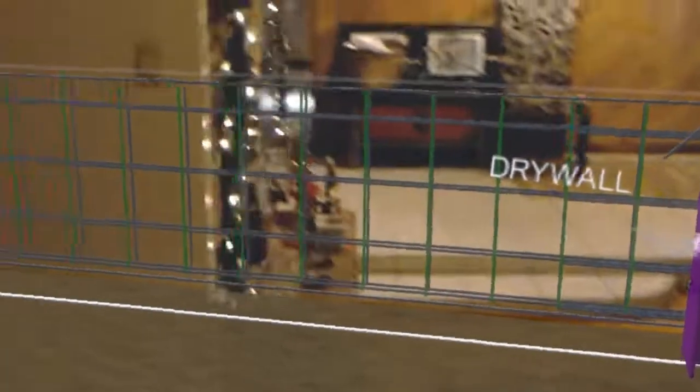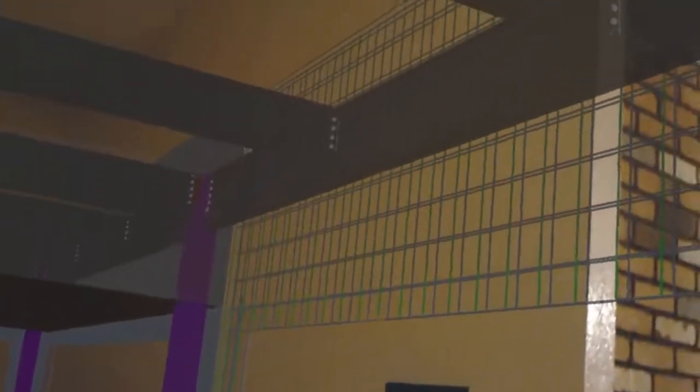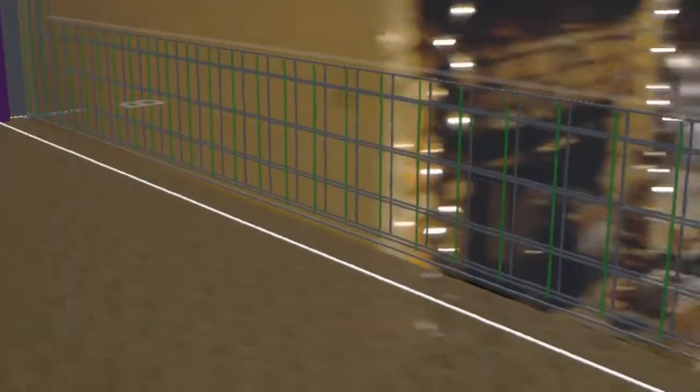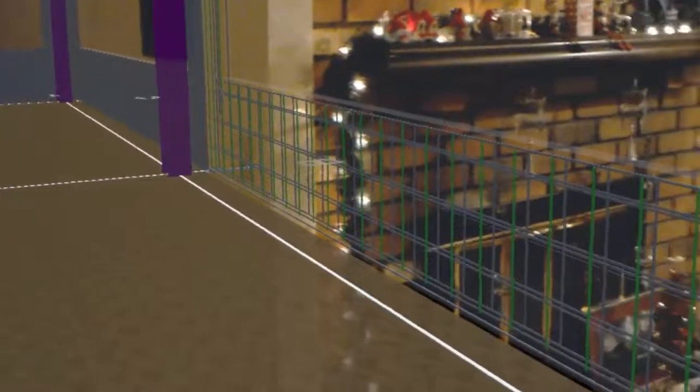And there we can actually see all the reinforcement inside of that panel wall. So what's really awesome here is that I can not only see the steel, the bolts, and the welds, but I can also inspect this from a concrete reinforcement point of view. And this is really great if you have something really complicated and you've colorized those differently by class inside of Tekla Structures. You can make it very easy to understand the different rebar and reinforcement that's being placed.